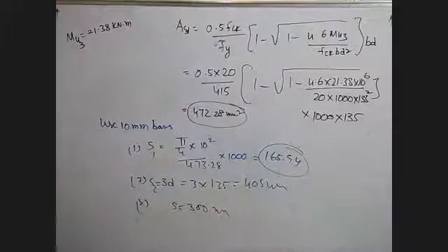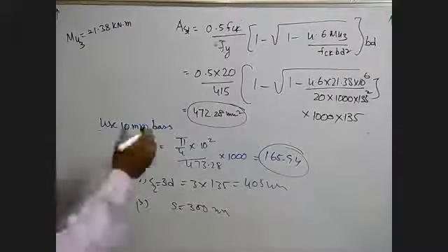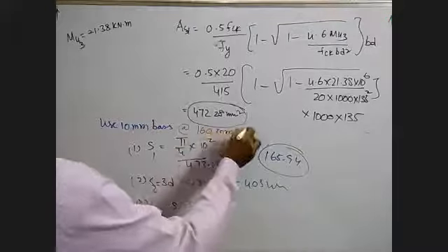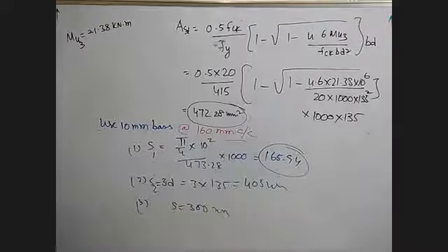So provide 10 mm bars at 160 mm center to center. So there is nothing new here. We have done it twice.